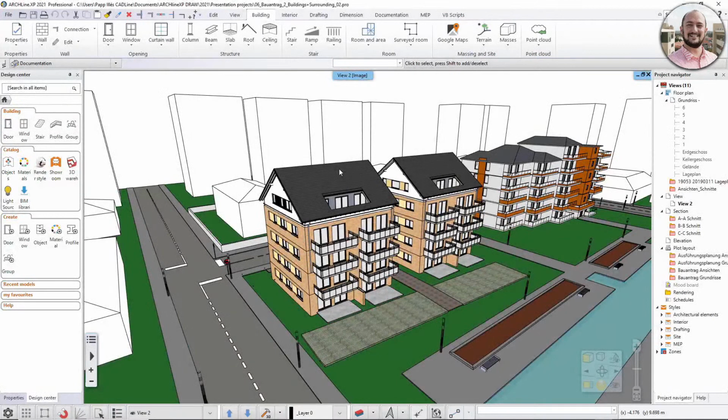Let's have a quick look at visibility filters. In this specific example, I would like to visualize this model in two different aspects. One, when I filter out a few things from the buildings and I don't want to see them. And in the other case, I will filter out the surrounding buildings. And for this, I will use two 3D views.